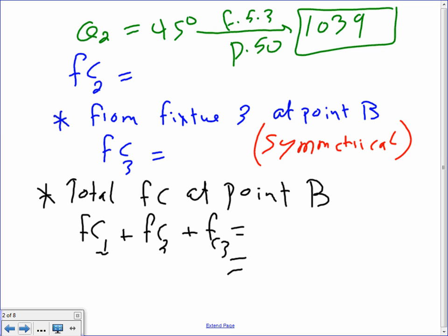You can see, Darren, if you look at the graphic, at 0 you have a low foot candle, then it keeps going up, up, up as you go forward to 45, and then starts going down again, right? Can you guys see the curve, how it goes down again? So the best foot candle that you can get out of the fixture is at angle 35. Can you guys see that? The best lumens at 35. Is that the best lumens? Okay, let's go do the calculation, will ya?